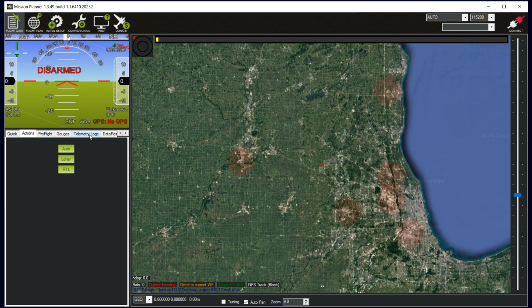There's a few other hidden tools in here that we'll use later, the telemetry logs and the data logs that are on the drone. So if we had a crash and we needed to do some analysis about why that would occur, we'd be downloading the dataflash logs and looking at vibration and other things and errors that are on the drone. And generally, we don't need that. We will need the flight logs in order to align our imagery with where the drone actually was at any given point in time. And we'll do this using this telemetry log tool. But for the most part, we'll use this while we're out in the field.